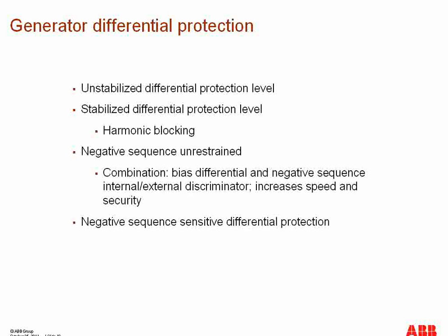For the stabilized differential protection, this protection can be made more sensitive, where the operation current is dependent on the stabilizing current. The largest measured phase current is taken as the stabilizing current in our ADC philosophy.